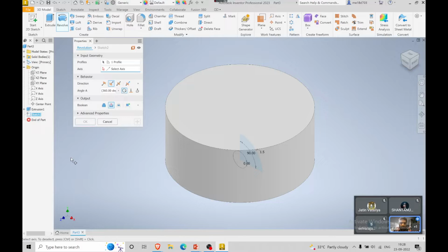Next, so there is also a fillet feature. So 1 mm. So maybe once we finish this upper aspect, we can do the fillet. So now there is another feature. Its diameter is 6, height is 7. So I'm going to draw another sketch of diameter 6.